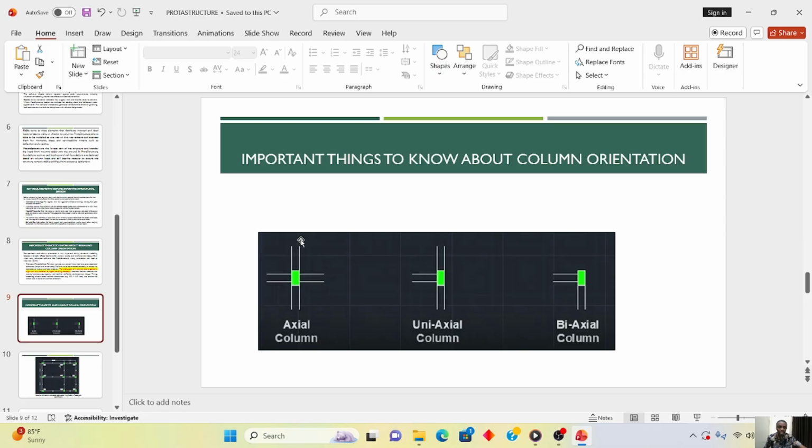That means the force coming from this side, since the beam is equal, counters the compressive forces coming against this column. The compressive force from this side and also from this side counter each other, because these beams are of equal dimensions. Therefore, there is no bending.